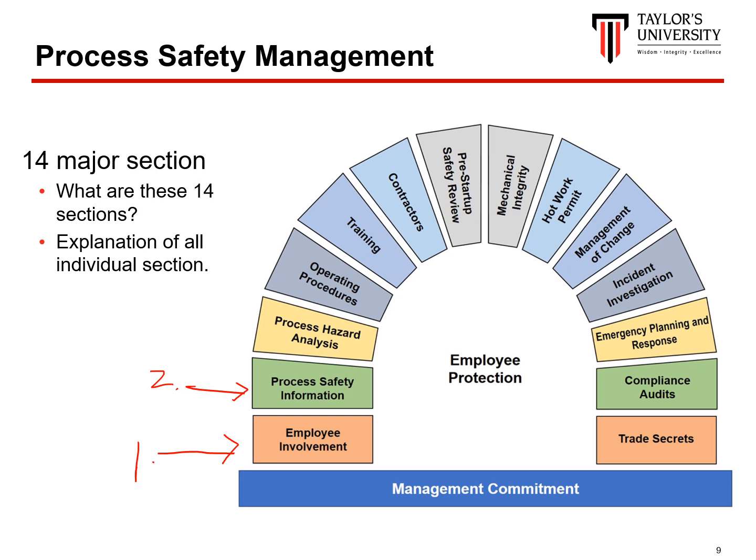And the third one is process hazard analysis. It has to be performed by a team of experts, including engineers, chemists, operators, industrial hygienists, and other appropriate and experienced specialists. The PHA, process hazard analysis, needs to include a method that fits the complexity of the process.